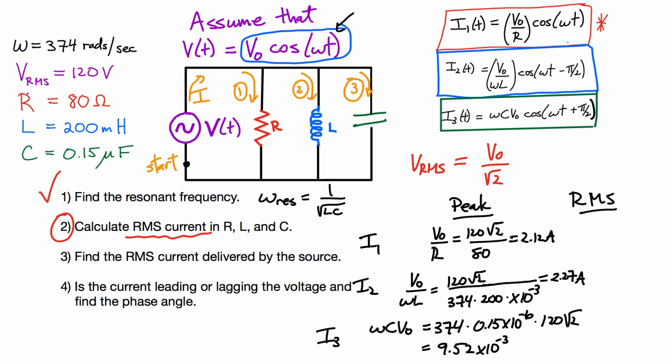All right. Again, if you want to get RMS values over here, all you have to do is simply not include that root 2 factor. So it should be root 2 smaller, right? Go ahead and maybe include this. So any RMS current is related to the peak, and you simply divide by root 2 if you're dealing with just simple sine functions like this.